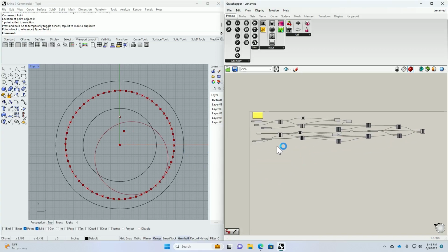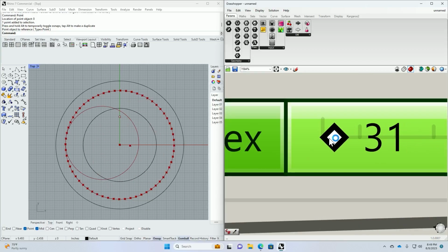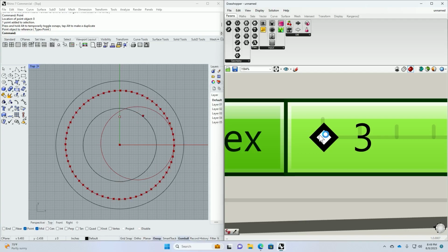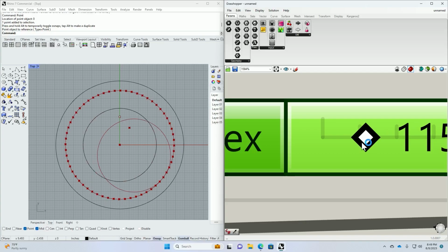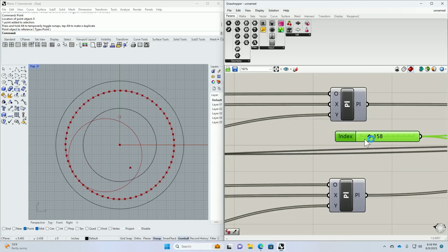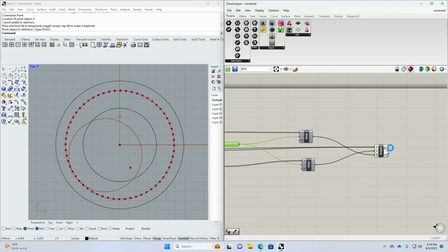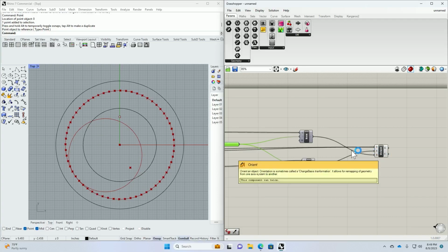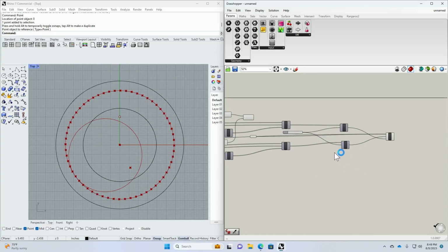See, so you can see it right there, and then as we go back in here, you can see how that point, as it goes, starts to draw out this path that we're trying to make. So you can see how the simulation works. You could advance it one step, insert a point, advance it one step, insert a point, advance it one step, insert a point, and then manually go and connect all those points. But if we're going to automate this much, we should automate that last step too.